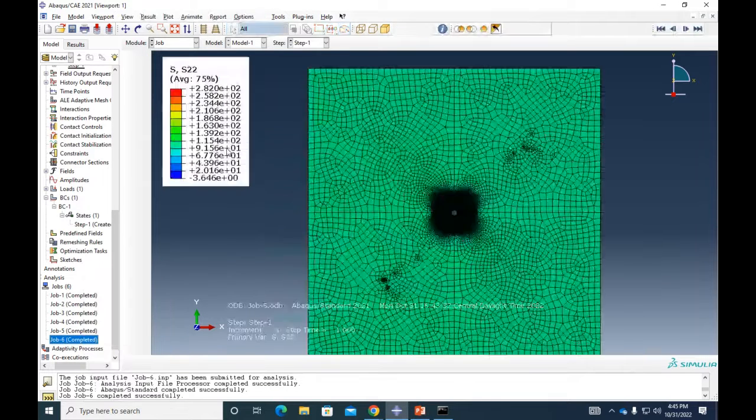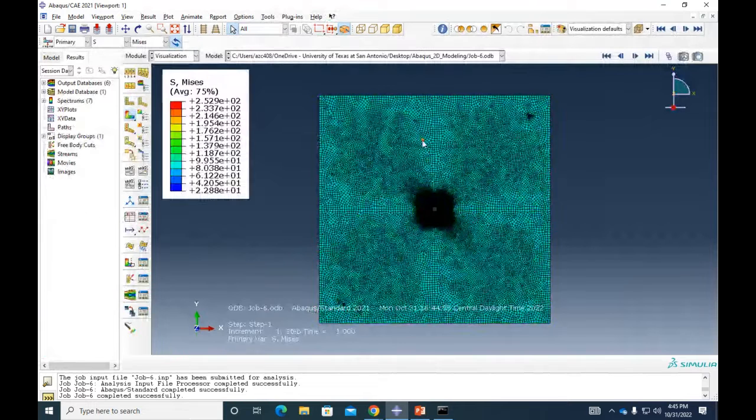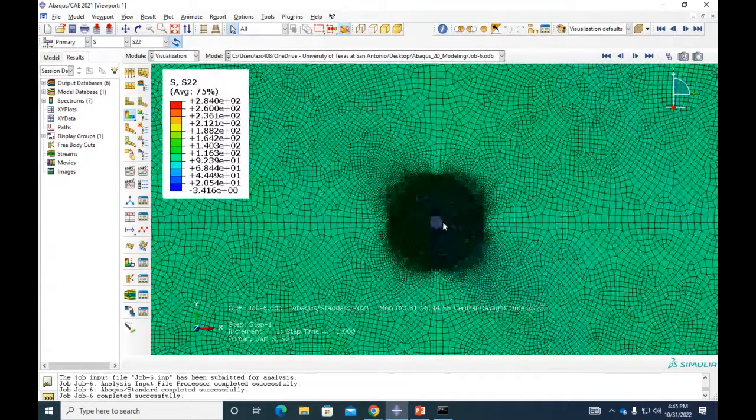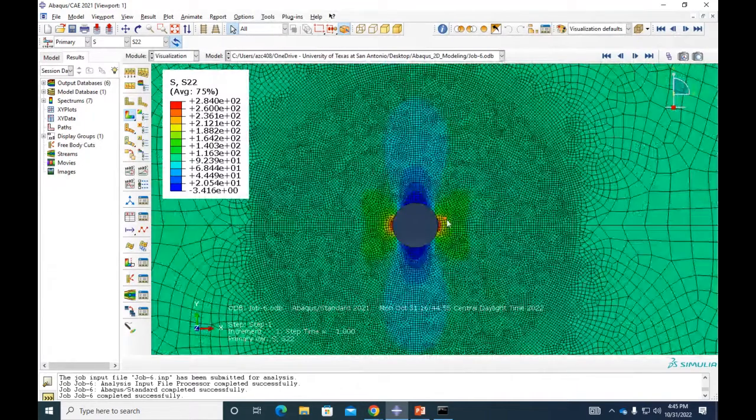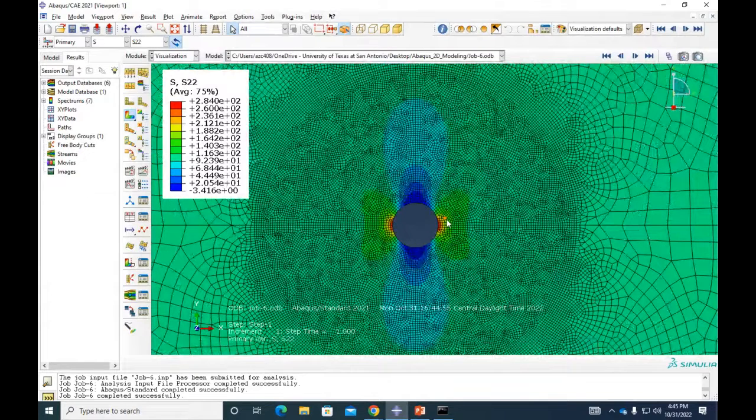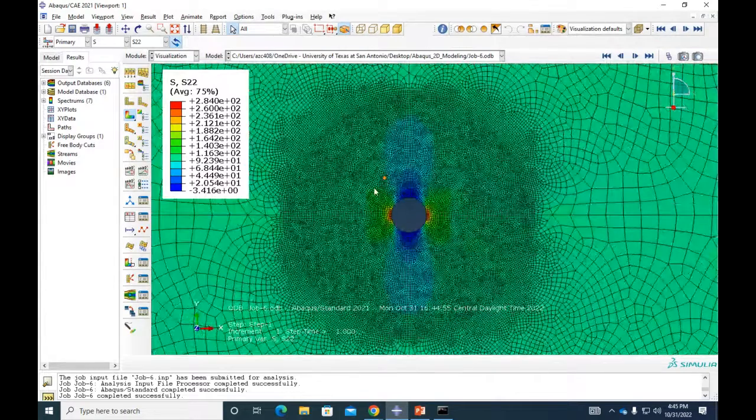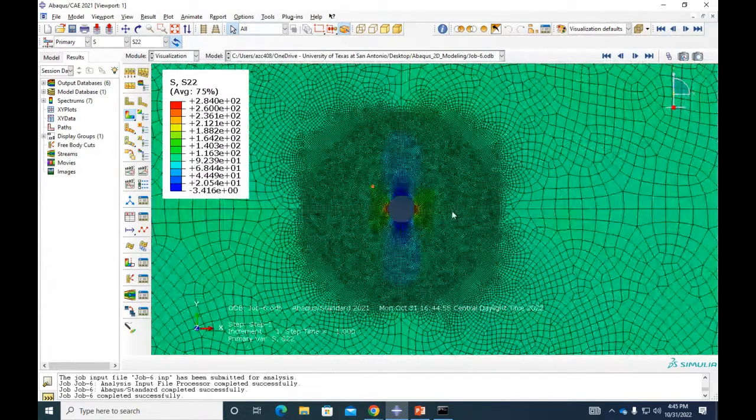Okay, let's check results. Now it's not rotating, so we did something good. And it only went to 284. So what did that tell us? The outer elements don't contribute a lot. So if we really want to improve this solution, let's do it one last time with the elements here really